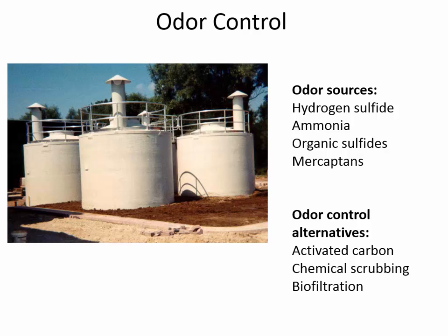Some of the materials: hydrogen sulfide is formed anytime there are anaerobic conditions in a wastewater, and so the hydrogen sulfide wouldn't be formed inside the trickling filter itself, but the hydrogen sulfide could be formed inside of a collection network where the wastewater is moving very slowly through a sewer pipe. Then it's possible that all of the dissolved oxygen is used in the wastewater, and then bacteria start to break down components in an anaerobic environment, and that's what will form hydrogen sulfide.